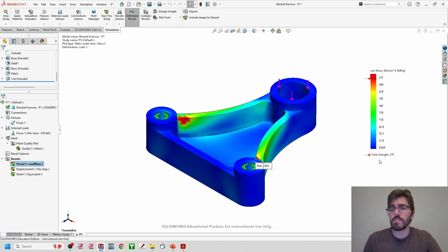And I referred to this earlier, but when you start to cross over this yield strength value, you get into this point of no return mentality where you start to enter into plastic deformation, where the part's going to get damaged or deform, or maybe start to crack. Or once you even get to tensile strength or ultimate tensile strength, you'll actually see the part shear or break or snap like you would in a normal dog bone test when you're testing the tensile and yield strength of a material.